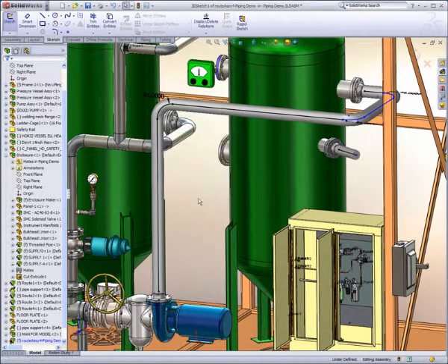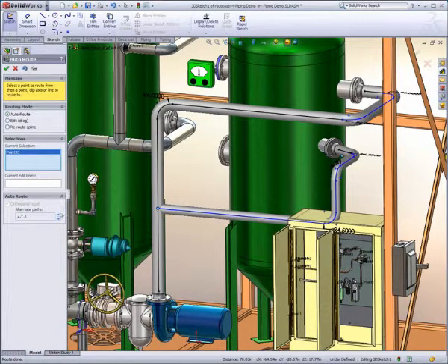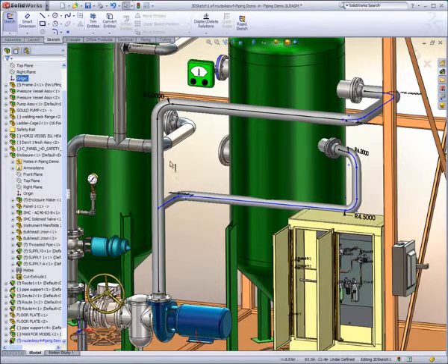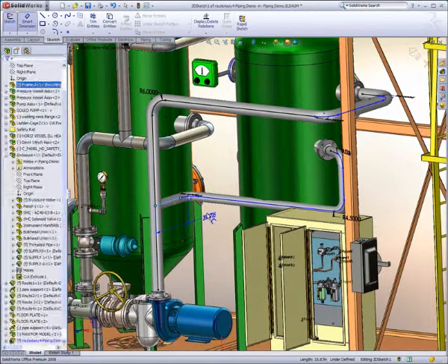Here, I'll connect a smaller flange to the piping spool. I can specify the intersection point by simply choosing a location in the existing pipe run. SOLIDWORKS can automatically connect the two locations for me, and all I need to do is modify the size and maintain desired clearances. I can either drag the pipe into place or use dimensions to size it appropriately.